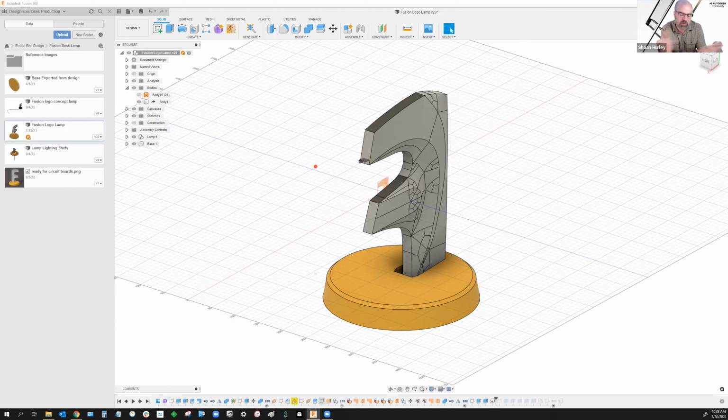But to the point here, before even Fusion had importing of scan geometry, every product out there... I used to do a lot of reality capture stuff and was on the reality capture team in the CTO. I would always get people saying, well, how about we just scan this motorcycle tank? It should be easy to go into Inventor or Fusion or anything, or AutoCAD. And it's like, no, it's tessellated. It's got all these points, and CAD being what it is, it wants to know the details.